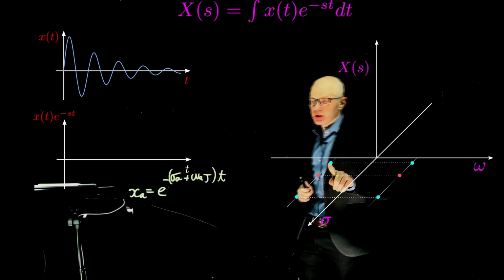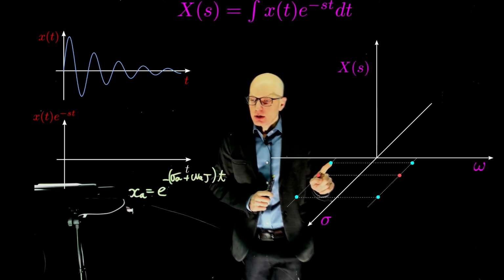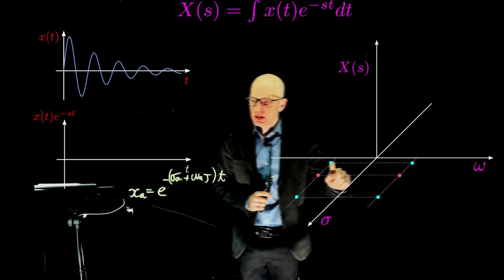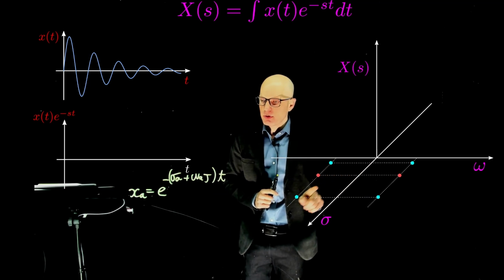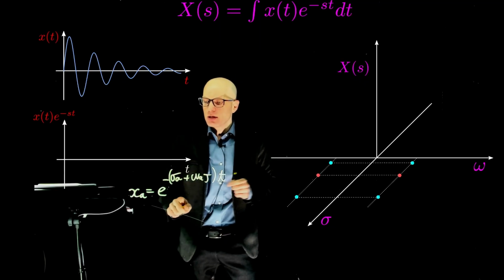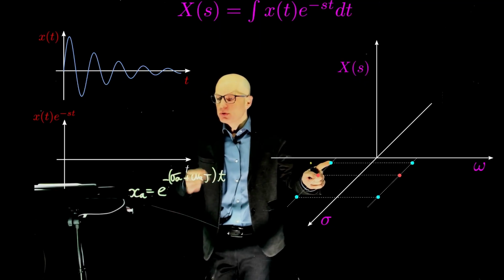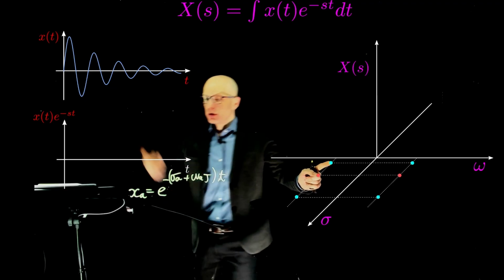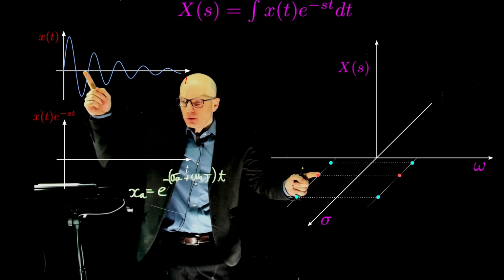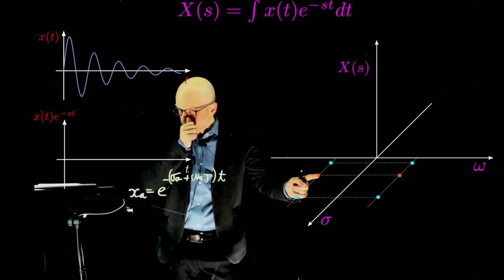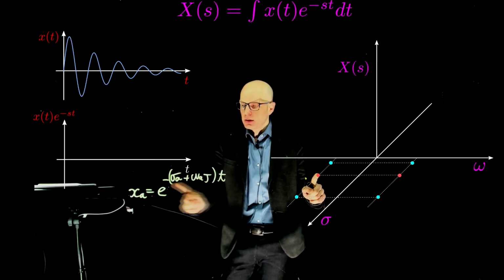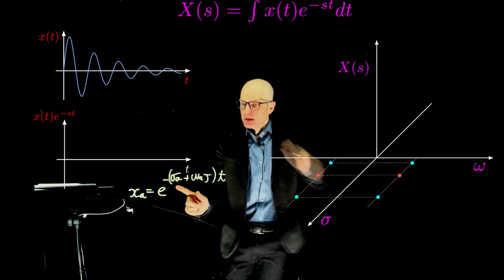Well, if you take this point here instead, we have the same frequency, but a smaller sigma, meaning that the signal we create through that point will decay slower than the actual signal we are trying to recreate, which is taken from this point here. Because the sigma is smaller, we have exponential of sigma t. The smaller the sigma, the more time it takes to decay.